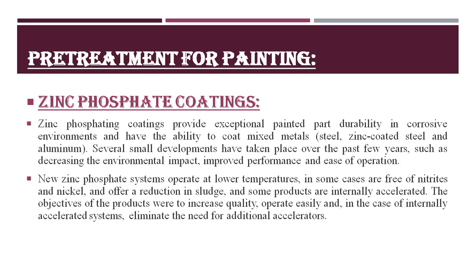New zinc phosphate systems operate at lower temperatures, in some cases are free of nitrites and nickel, and offer a reduction in sludge, and some products are internally accelerated. The objectives of the products were to increase quality, operate easily, and in the case of internally accelerated systems, eliminate the need for additional accelerators.